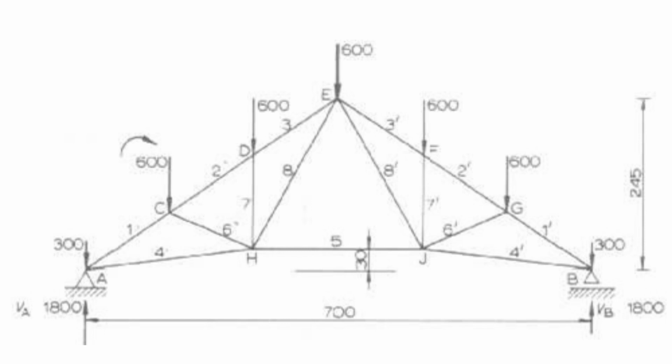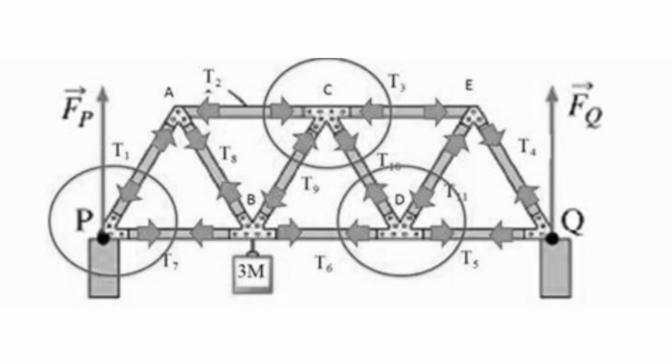On the basis of these assumptions, each member of a truss can be treated as a two-force body. It follows then that forces at the ends of any member must always be directed along the axis of that member. Therefore, an individual member can only be stretched or compressed. Hence, for the purposes of force analysis, a truss is always considered to be an assembly of two-force members, in axial tension or compression, joined by frictionless pins.